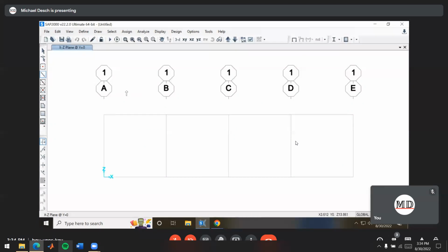And we see we have an arrow that's pointing up. Now this means we're in the drawing tool right now. So the way we draw members is we left click where we want to start it, and it's going to be drawing a member to where we left click again. So I started there, and then I clicked here, and it drew that member. Now we see it's still going, so we can draw many members kind of in series here. So the next one I can do, I can click here, and then I can go and click here.